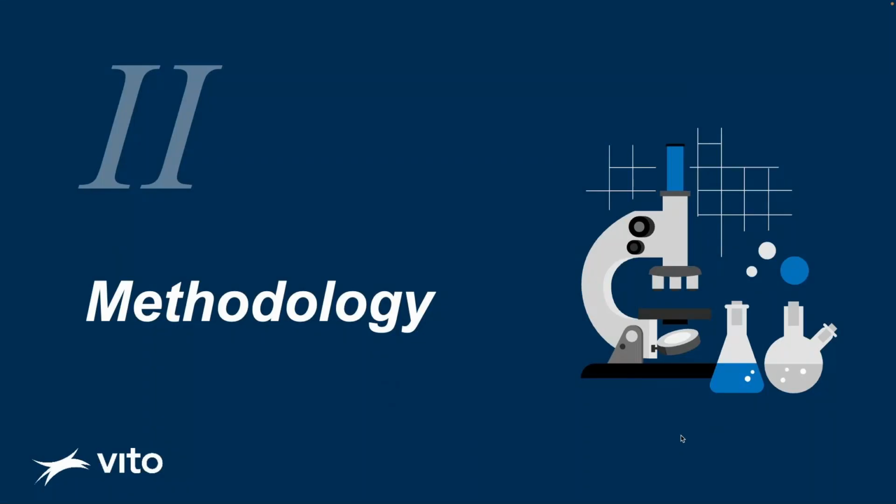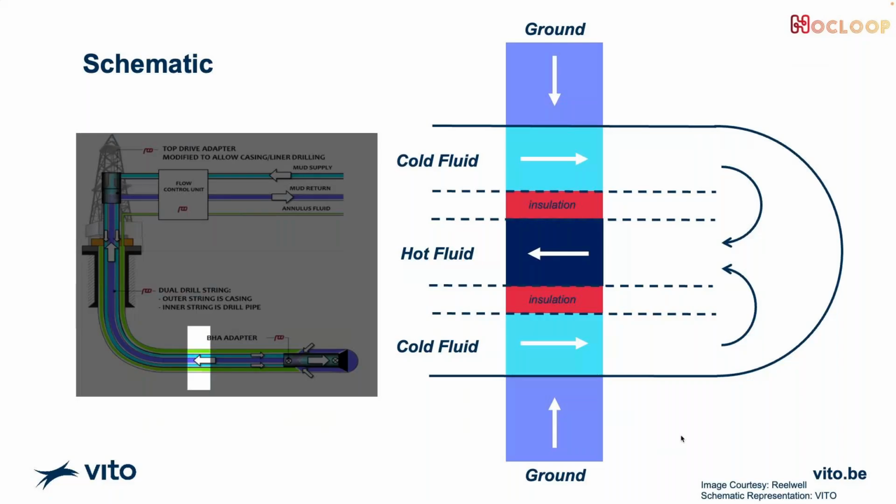Now, if you look at the methodology, if I go back to the same image, and if you look at a smaller section in this horizontal section of the geothermal power plant, you will realize something which is very common, or that we have a functionality in SU2, which is seamless periodicity. Also, we try to choose an area which is over here, because this is a horizontal section which is approximately 2 to 2.5 kilometers long, and at the center the properties are more or less steady state, and they do not change as much as compared to if you go to one of the areas on the other side.